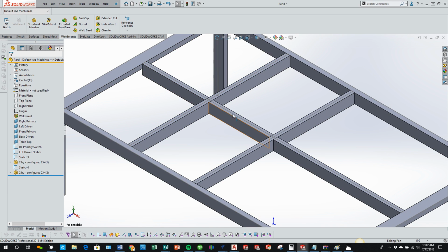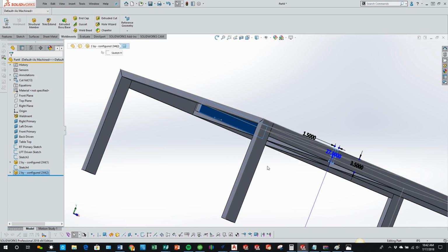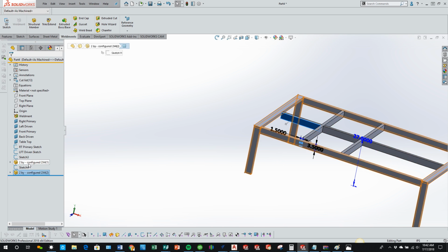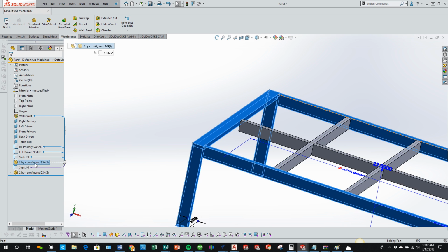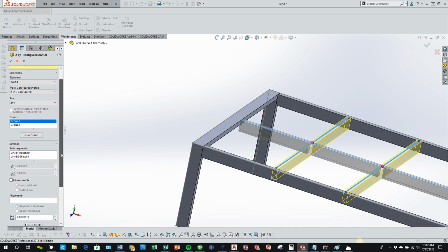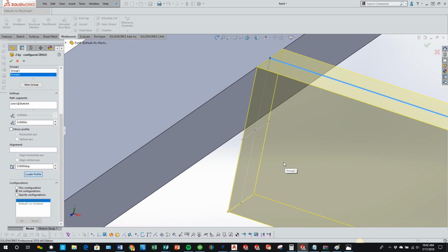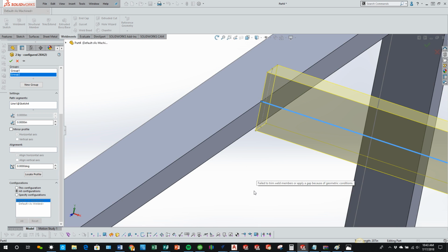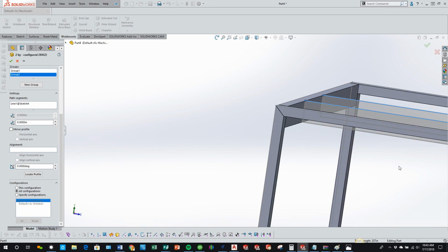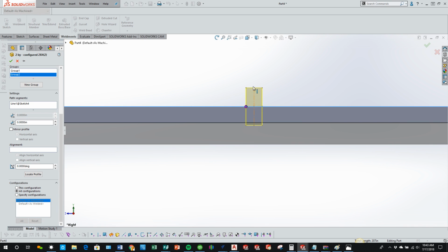Now looking at this weldment or these beams here, you'll see that this is extending down a little bit. So there's some functions that I might have to do here where I need to come back to configure 2-4, that first one that I did, and create a new set of groups and rotate this profile 90 degrees, or I can relocate this profile at 90 degrees. And what I mean by this is simply coming in, and let's say group number 2, I want to come in and say, let's locate this profile, and I want to make it so that it's locked to this point. Now, looking at this point here, you go, okay, hang on, Peter, this is now offset to the right of that sketch line, and it's up high.